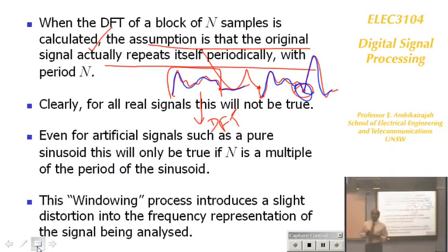So in a DFT, when you do analysis, high frequencies will be introduced unnecessarily with this windowing technique, because we're taking a group of samples, which means there's a window. Like if 10,000 people are going, and I only want to look at 100 people, what do you do? You look through a window to 100 people. If I want to see 1,000 people, you use a window of 1,000.